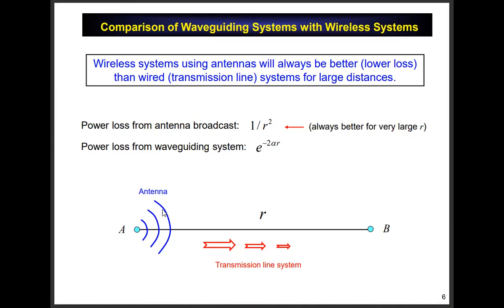So it's natural that the power density, the Poynting vector in watts per square meter, is going to fall off like 1 over distance squared. It may be more concentrated in one direction than another direction. That's what's called the gain of the antenna. But still, in any direction, it's going to go like 1 over r squared, or some constant over r squared. So that's what this is.